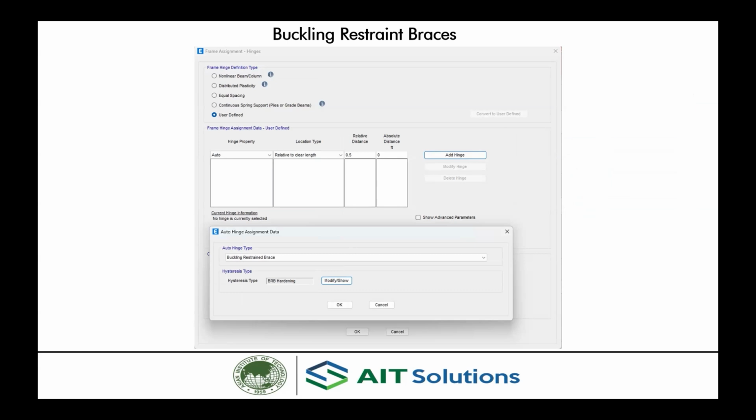So not only is ETABS covering our typical elements, but some special elements are also covered, like buckling restraint braces. And you can use the buckling restraint brace section and the auto buckling restraint brace hinges to model the BRBs as nonlinear as well in your tall buildings. Or again, BRBs can also be used for retrofitting of existing small structures as well.